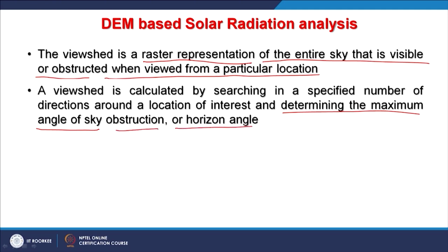Whether parallel to the horizon you can get signals or energy is generally not possible. So, what angle you would like above the horizon, say 5 degrees or 10 degrees, this cutoff, 5 degrees minimum, is always required. Otherwise, at the edges you will not have anything.